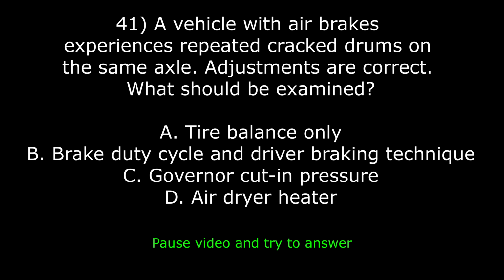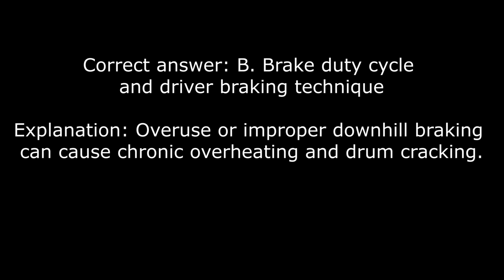41. A vehicle with air brakes experiences repeated cracked drums on the same axle. Adjustments are correct. What should be examined? A. Tire balance only. B. Brake duty cycle and driver braking technique. C. Governor cut-in pressure. D. Air dryer heater. Correct answer, B. Brake duty cycle and driver braking technique. Explanation: overuse or improper downhill braking can cause chronic overheating and drum cracking.